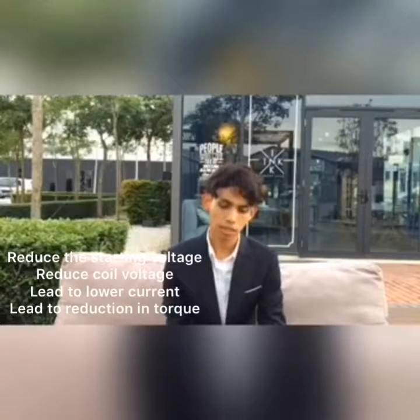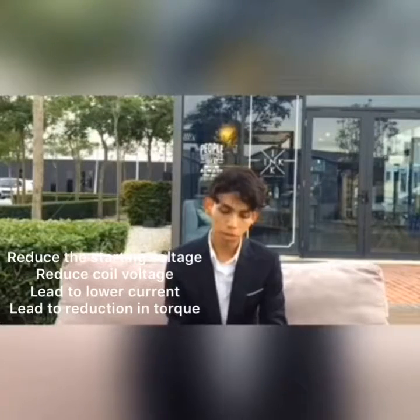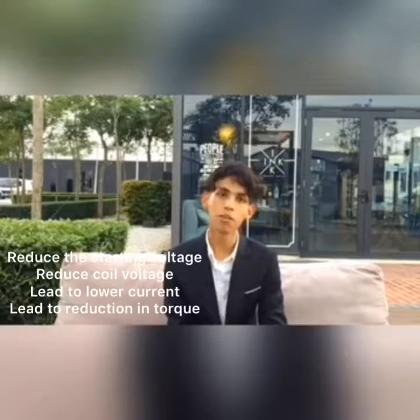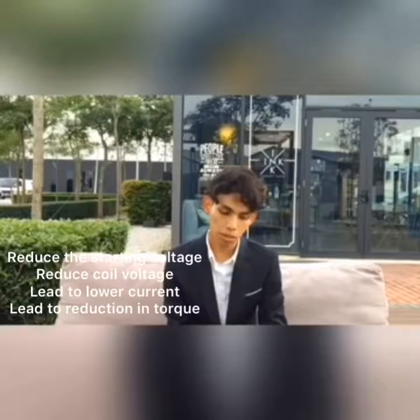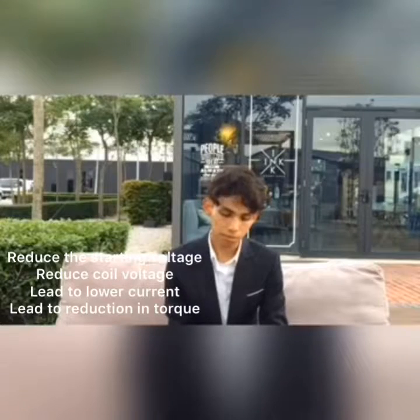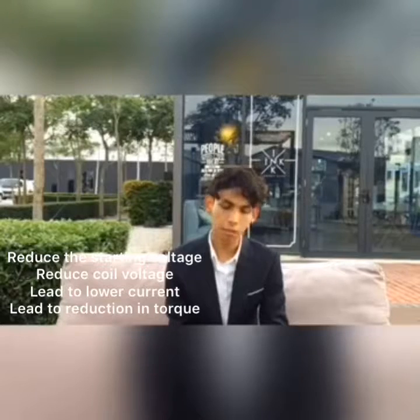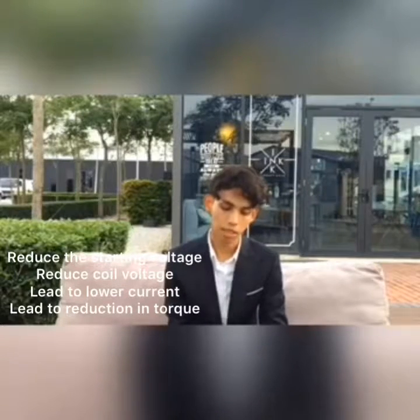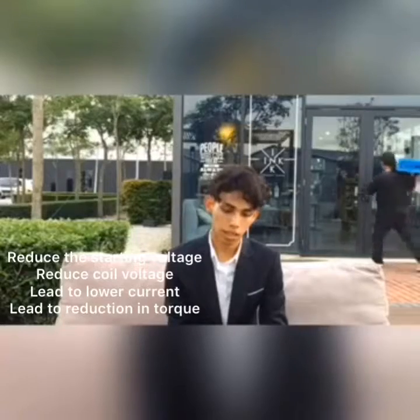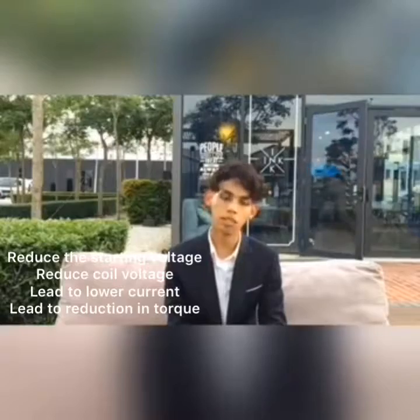First, to reduce the starting current, we need to reduce the voltage. In Star configuration, we reduce the coil voltage to around 58% compared to the Delta configuration. Lower voltage will lead to lower current. So the current in the coil in Star configuration is around 58% of the Delta configuration, which leads to a reduction of torque. Star configuration torque will be around 33% compared to Delta configuration.